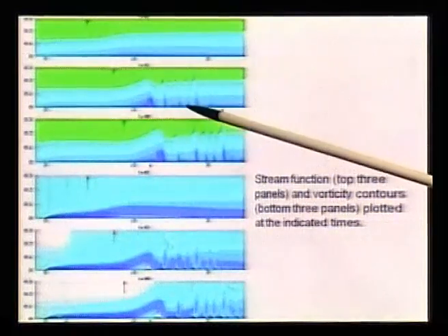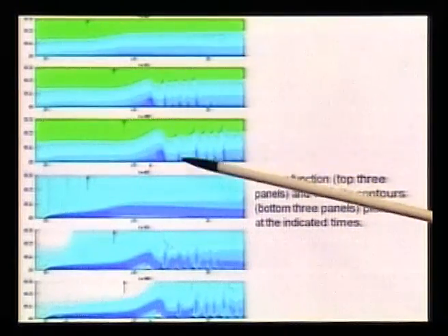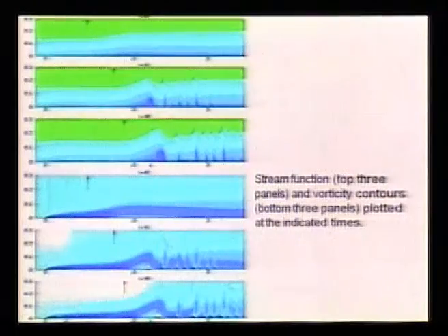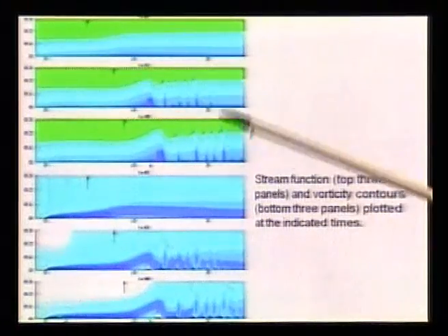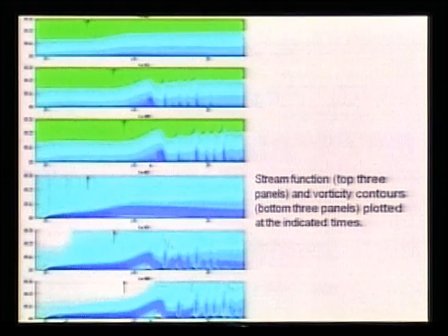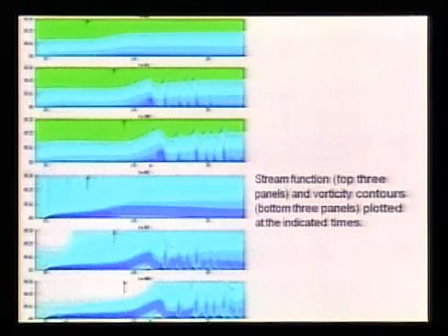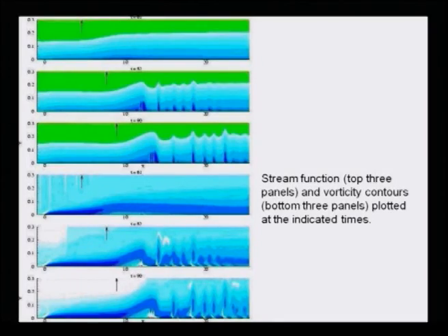And from this you can see this undulating streamline structure here, right. So, you can see that there is some kind of vertical eruptions taking place from inside the shear layer. Certain structures pierce through, and this is what we are calling vortex induced instability. And you can see similar vertical eruptions in the vorticity contours. Okay. So, I think I will stop here. In the next class we will give a theoretical model of how it creates this instability.